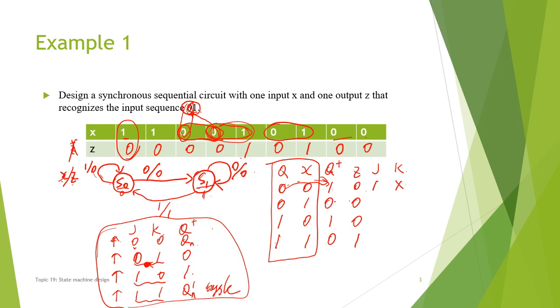Now the next is changing from 0 to 0. So no change corresponds to either; we can think of this as the no change state, but we can also think of this as the reset state, right? So in this case, J has to be 0, but K again, we don't care. Then the next one, 1 to 1, which means either no change or set.